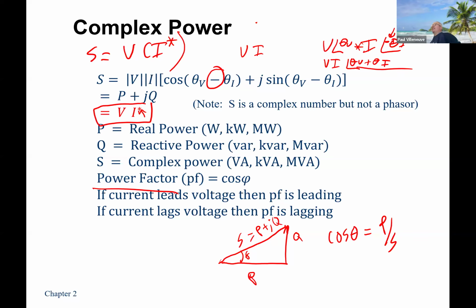And it's not a positive or negative power factor. It's leading or lagging. So remember when you used the term at the beginning of class, I think it was leading, those terms are reserved for us. Leading and lagging is what is the current doing? Is the current leading or is the current lagging? And why am I harping on this? Because I know a lot of you aren't going to work in the utility industry, but if you work in renewables and you try to connect to the grid, you'll often come across the term: my inverter-based PV system can operate at a 0.95 leading or lagging power factor.